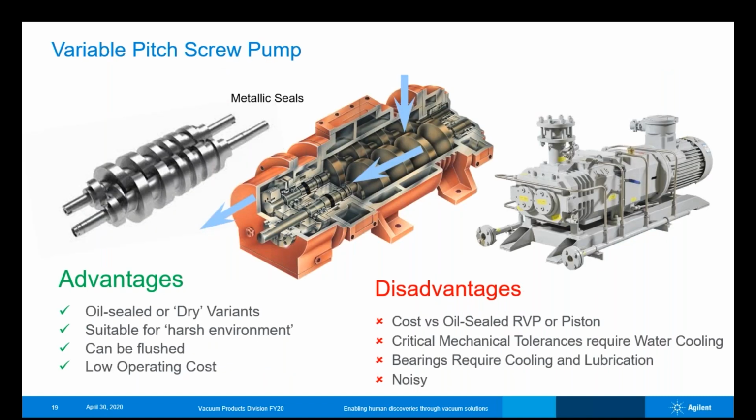The screw pumps are common with industrial customers that have a very aggressive process that might be attacking different metal surfaces, and might prefer to use the screw design. One thing to note is that there are a couple of varieties of these. We can have oil sealed or dry variants, and we can have screw pumps that act as a booster pump, and that would be a fixed pitch screw here. So picture just having two mechanical screws turning together. We could imagine there's a little spiral pathway for gas to move along.